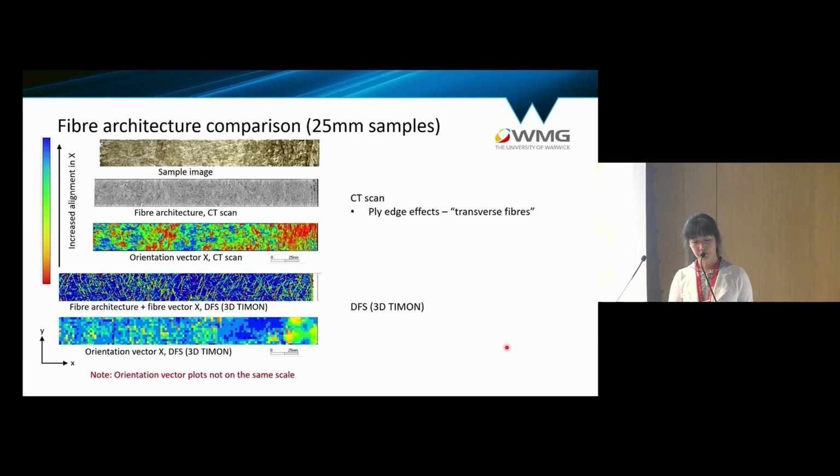So I've then compared the CT scan results with the simulation. When we were doing the CT analysis for this project, I gave my CT scan colleague a very long wish list of things I wanted them to do, like, can you segment individual fibers, and give me information such as orientation, fiber waviness, and how the tow geometry has changed.